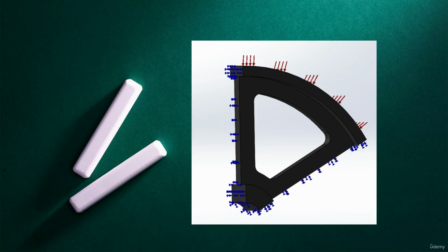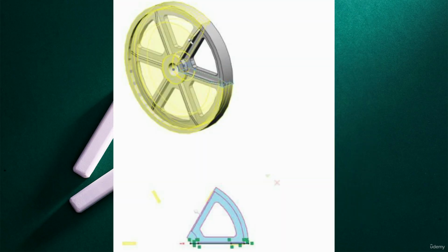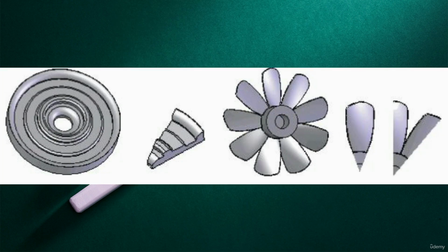When modeling objects with circular symmetry, the geometry, the restraints, and the loading conditions are similar for all other segments that make up the model. And the circular symmetry restraints can be applied for solid models and for static analysis only. There must be defined two similar planar sections and the axis of revolution. And here we can see the disk and the fan with its two corresponding segments for study analysis.